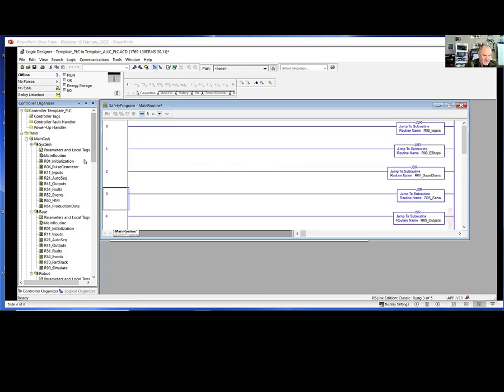So their programs all have these routines in them. They have initialization. Their initialization is in structured text. It is not in ladder, but I've made mine in ladder because not all PLC programming software has the structured text add-on. That's one problem with it. So if I were doing a class and I was teaching somebody who doesn't use structured text, it would be better for this initialization routine to just be simple ladder. All initialization does is it puts initial values into things like resetting the machine.